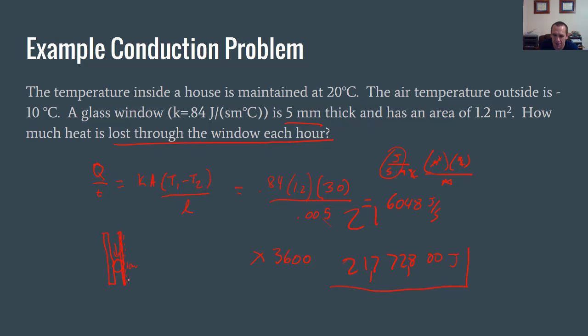So this is not going to be the same temperature as the air over here, because conduction happens fairly slowly in air. It's a good insulator. Same thing on the outside, unless the wind is blowing and constantly putting new air here. The air here is going to be slightly warmer because it's up against that warm window. And so we design windows to limit heat flow.